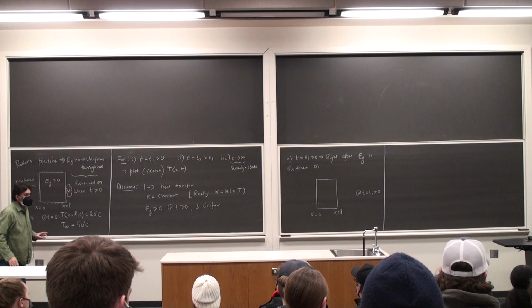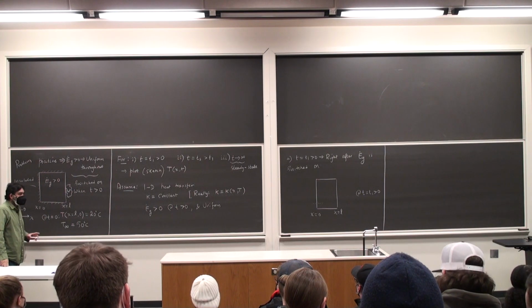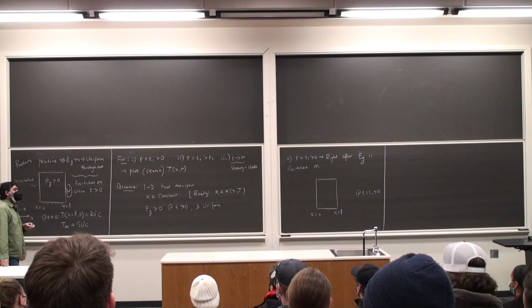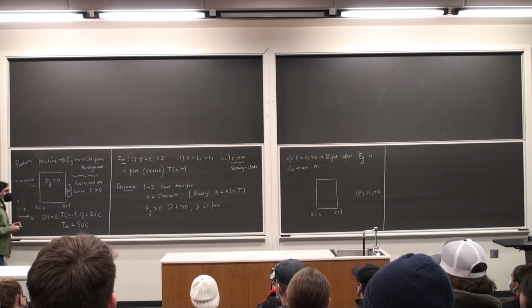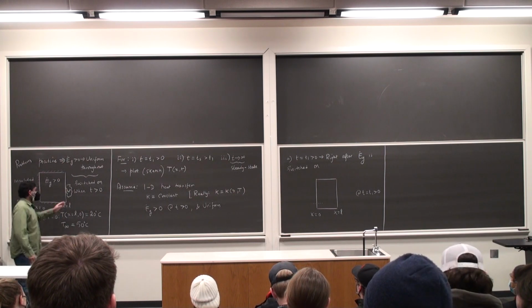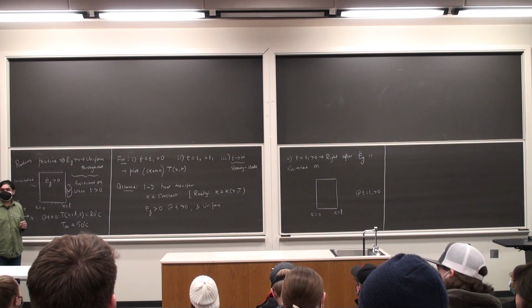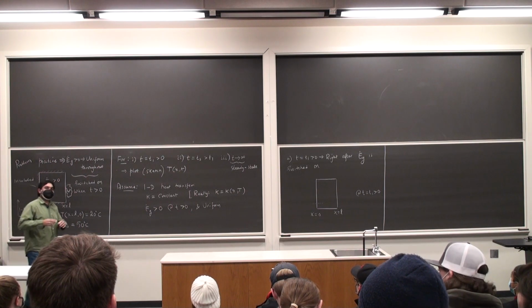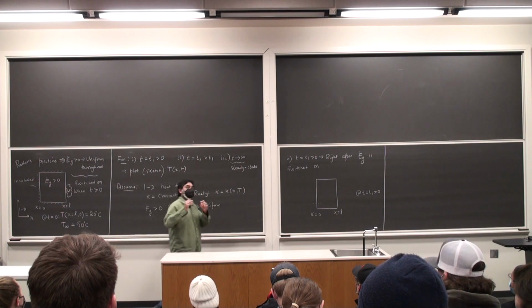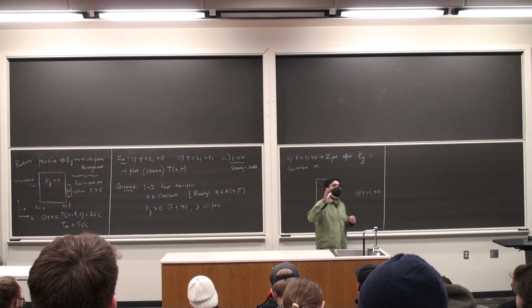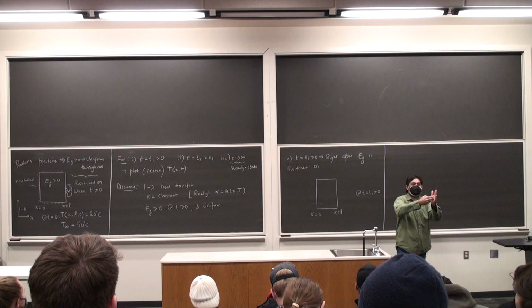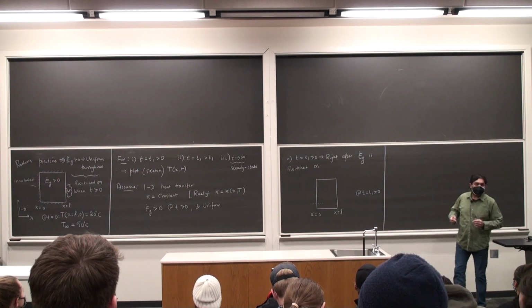I think it should be positive because the T infinity is greater than T. I like that. You see, this is hotter than that, so obviously the direction of heat transfer has to be from the ambient to the wall. So we don't even need to think about the physicality of the slopes and so on from the point of view of the derivatives. Just a simple heat transfer. If something is hot and something is cold, the damn thing has to go from hot to cold. Okay?